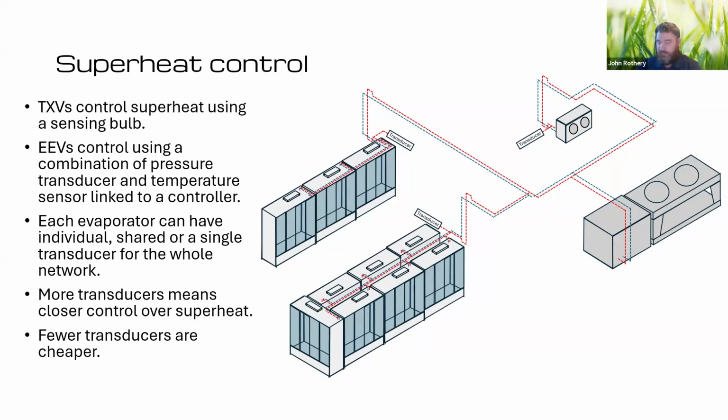So say, for instance, a manufacturer like Carel, they've been around for a while now. It's just knowing and interpreting the parameters that you need. It's definitely overwhelming, without a doubt. One of the issues on, say, the Carel front end is when you get a graph and you switch between various readings, you have to check the scales, because you can set it to auto scale, which makes things maybe not align.